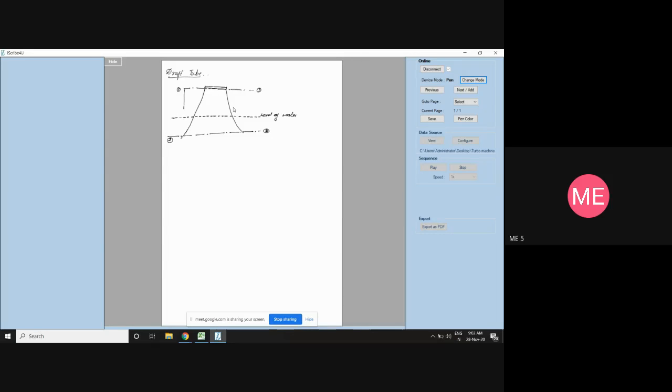And this height, I will denote as HS, and this height I will take as Y. And here, what is the pressure acting at this level? It will be atmospheric, so P atmospheric. And this water, whatever it is seeing here, below the water level, is called the tail race. Tail race is nothing but an exit water, where from the exit of the turbine it goes to the channel. That is called a tail race.